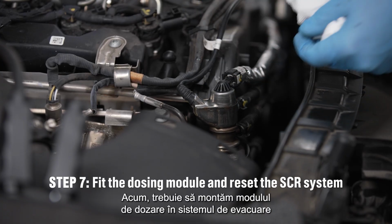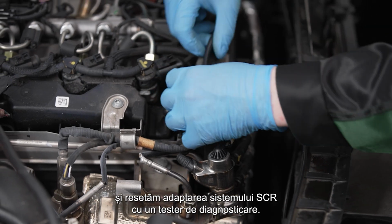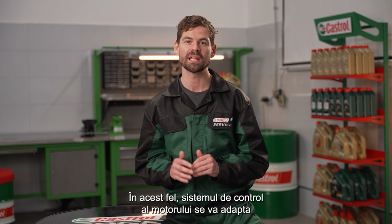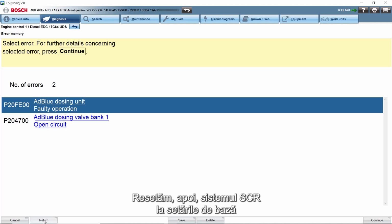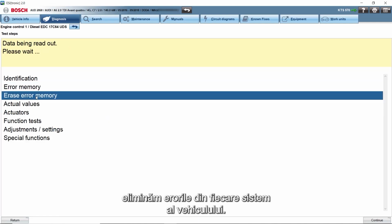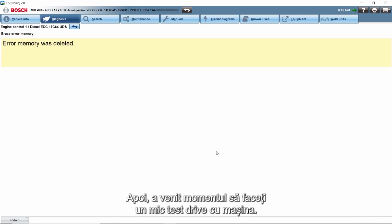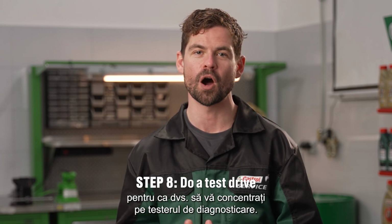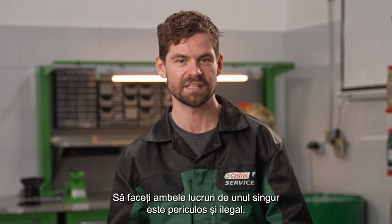Now, we have to fit the dosing module to the exhaust system and reset the SCR system adaptation using a diagnostic tester. That way, the engine controller will adapt when we do a test drive under road conditions. We then reset the SCR system to its basic settings and clear the errors in every single one of the vehicle's systems. Then, the time has come to take the car for a little test drive. Remember that you'll have to have another person driving, so you can focus on operating the diagnostic tester. Doing both things by yourself is dangerous and illegal.